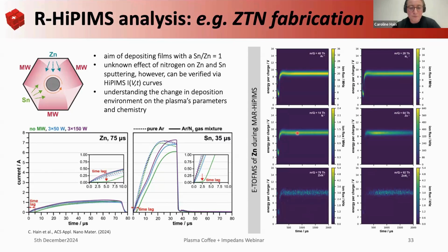So with that, we're able to control the energy of most of the ions, rather than having this very spread out tail. For instance, for some HiPIMS conditions, it can be from 5 to 20 or 30 volts. Here we have a very narrow energy distribution.